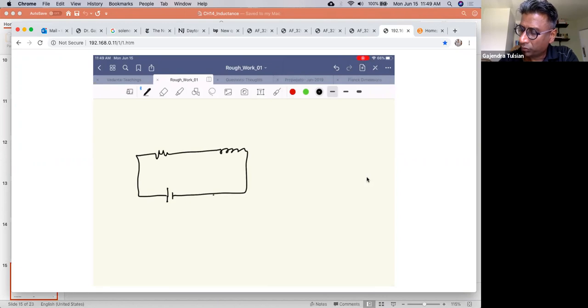So we're going to use Kirchhoff's rule. We'll start off in this corner and go counterclockwise. Kirchhoff's rule is that the sum of voltage across elements should be 0. So we'll go across this element, and by the way, let's call this I(t), the current as a function